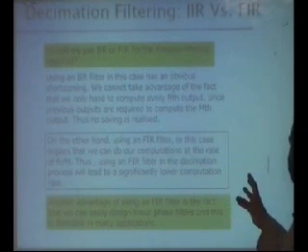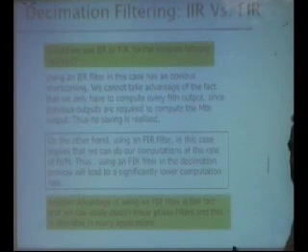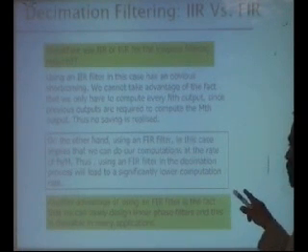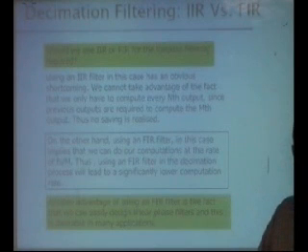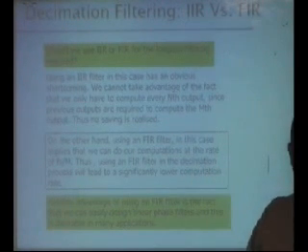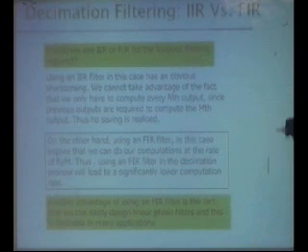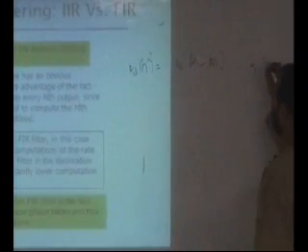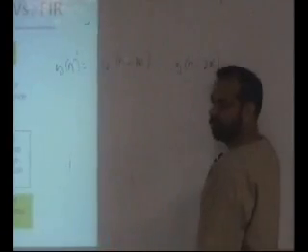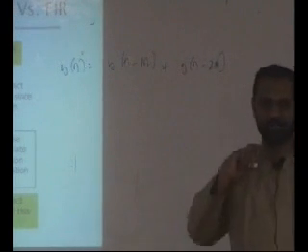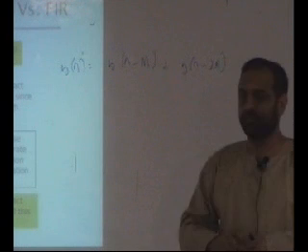But primarily what we did was write the IIR equation in a manner where you only require the mth whole sample. There is recursion, but the equation is written where y of n only depends upon y of n minus m, y of n minus 2m. It is very difficult to write it in this manner, not very simple or straightforward.